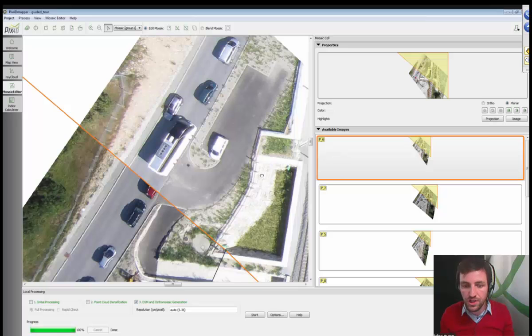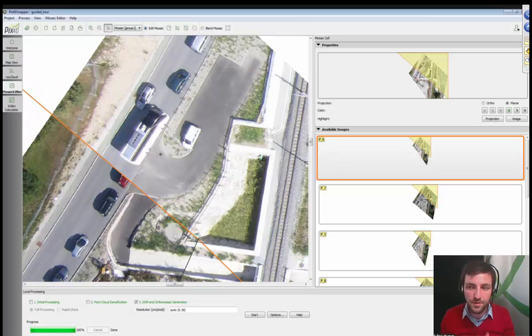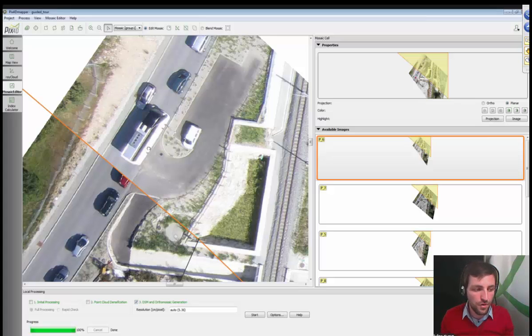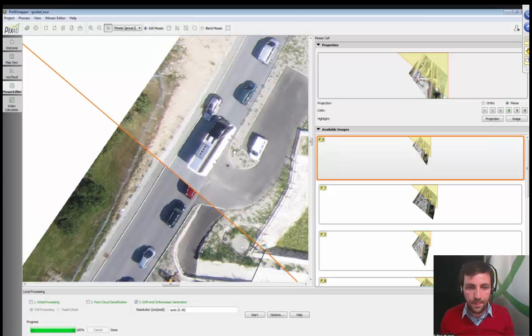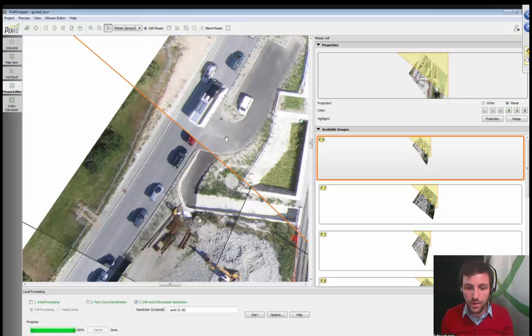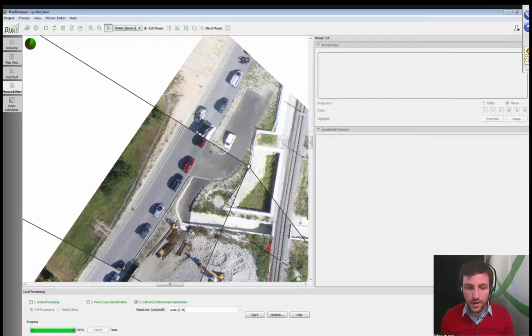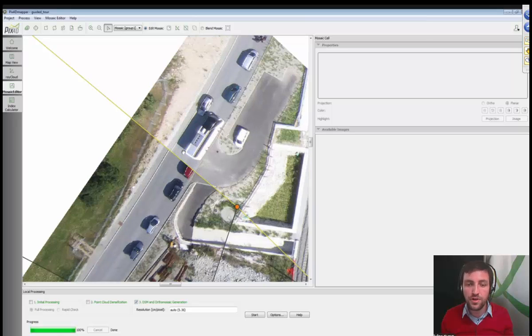By using planar projection, you are not accurate anymore. So you are not rectifying for perspective, so everything which is above the ground will potentially have a wrong measurement. In that case, it's not very bad because it's just to make it a good-looking image. But you have to be aware that when you use this option, it will look much better. There will be no distortion. However, the measurements that you do there, if you try to measure the roof, it will not be exactly the right size.